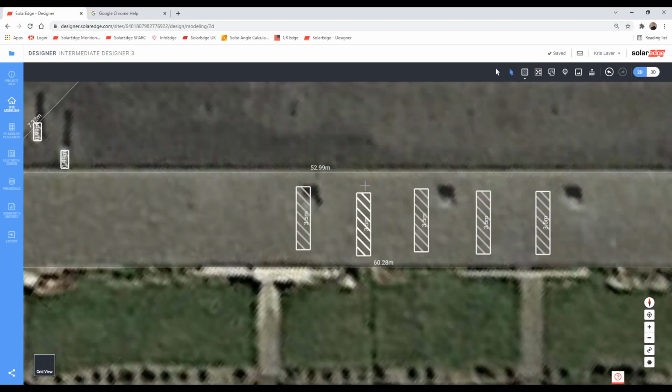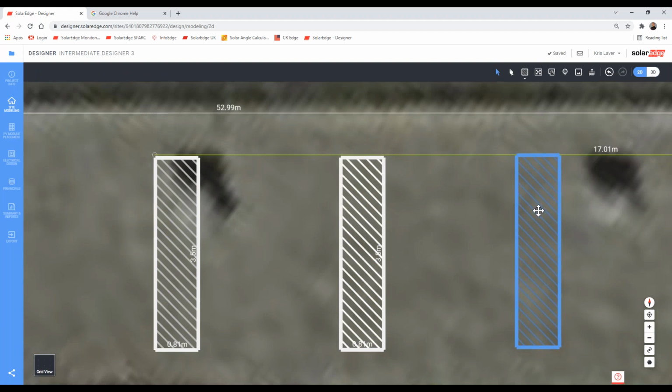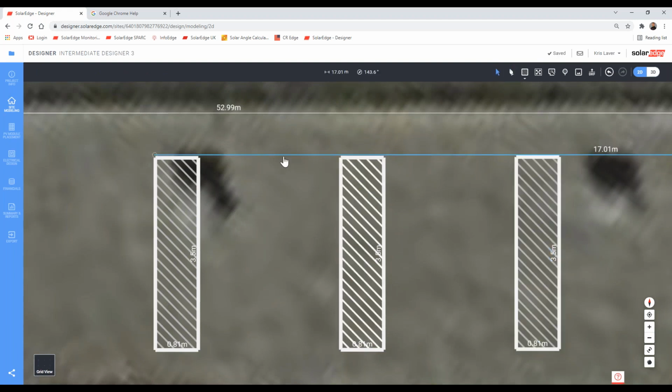They're much the same, keeping them in line. You can just offer yourself up a guideline, ensure that they touch the top, and again be as precise or as unprecise with it as you want. And if you want to ensure that there's certain distances apart, you can simply start your guideline, click the line anywhere to terminate it, press Escape, press on the line.